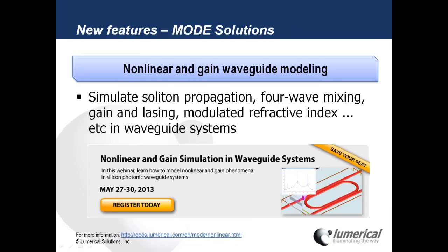In terms of other new features, Mode Solutions now supports nonlinear and gain waveguide modeling. This allows us to simulate soliton propagation, 4-wave mixing, gain and lasing, modulated refractive index, and so on in waveguide systems. And the nice thing about doing this in Mode Solutions, which is a very, very fast propagator in the time domain, is that it allows us to simulate very large-scale waveguide systems, as well as to simulate for long